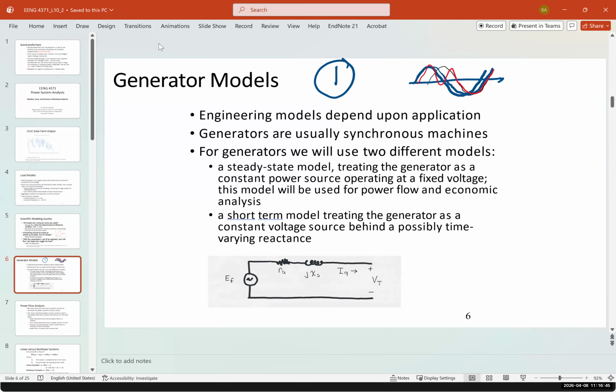let's say you have a steel factory and you have these huge furnaces and all of them mostly work on electrical. It's not like they can easily turn that on. It's going to have an effect on the generator, so you have to be able to match that. Usually what happens is the frequency and the voltage dip a little bit, and then the generator picks up that load. It takes a few seconds. But as mentioned, it's like a creature that's alive. It's a dynamic thing that you have to constantly manage. Yes. But it does it to a very certain degree.